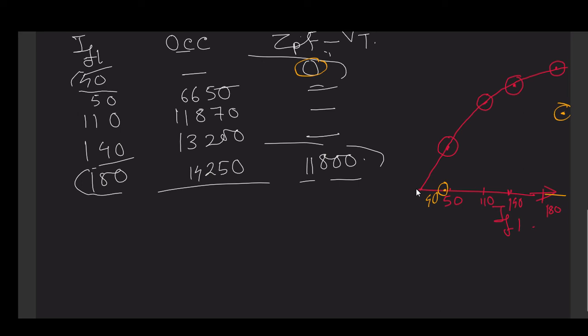Now in the short circuit characteristics, we know that generally armature resistance is so small that the armature leakage and armature reactance are producing almost complete demagnetizing action.